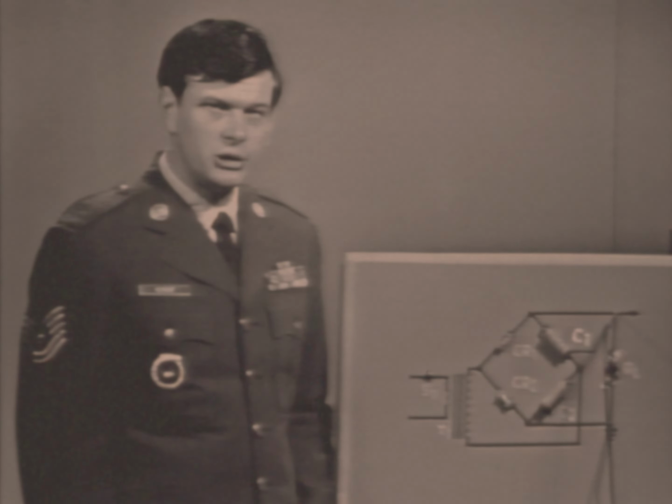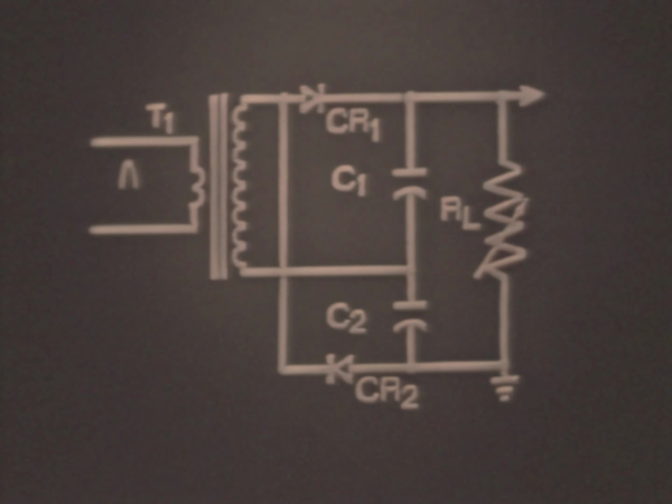So, let's return to the voltage doubler circuit and discuss circuit operation, including current flow for C1 and C2 on both the charge and discharge cycles. We'll begin with the review of the charge path for C1 on the positive alternation of the input signal, which, you recall, forward biases CR1. Then, on the negative alternation, C2 is charged by forward biasing CR2.